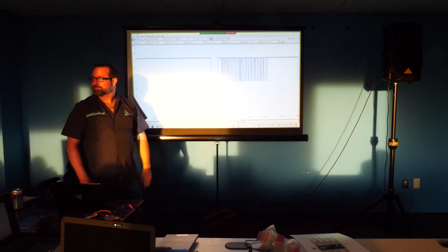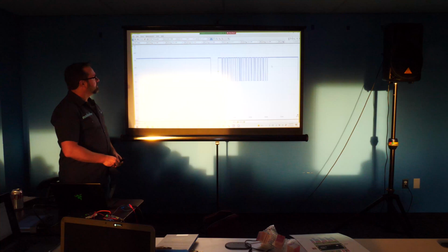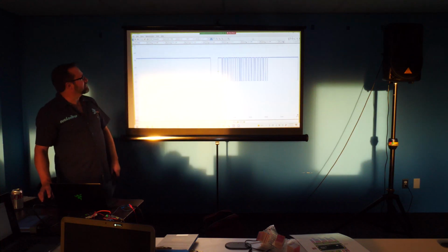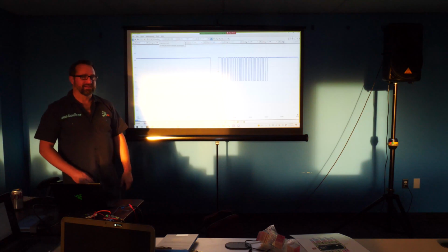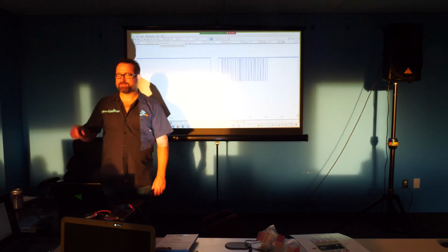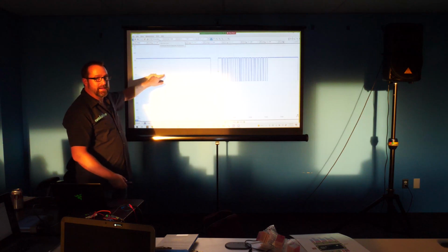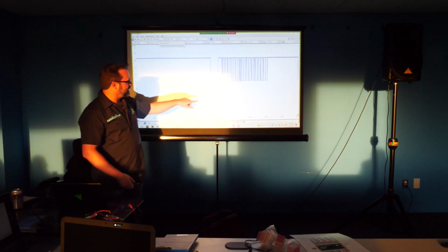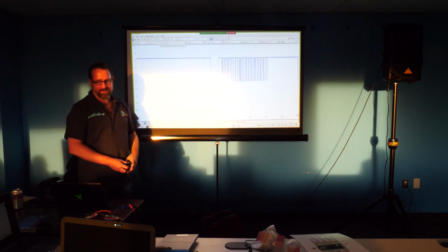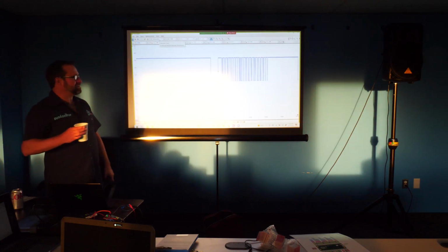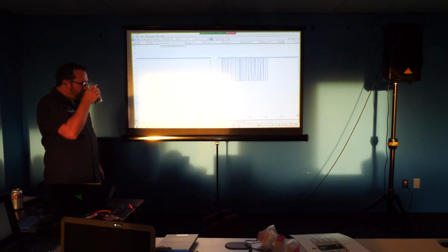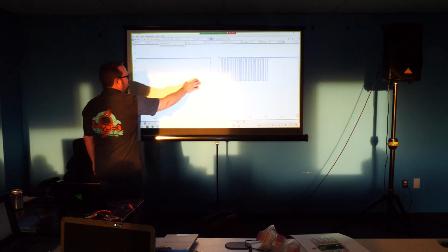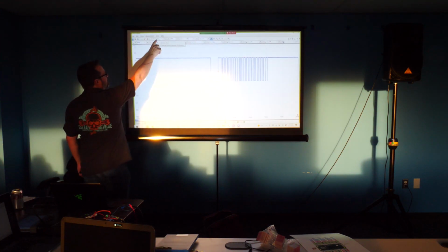Are those all milliseconds at the bottom? What's weird about an oscilloscope, which I think is stupid, is that this is a carryover from the original CRTs that they always have in sci-fi movies. I prefer using it like a DAC, data acquisition equipment, where it's just Y versus T. Anyway, the oscilloscope has a grid, and you set the grid timing with milliseconds per division.